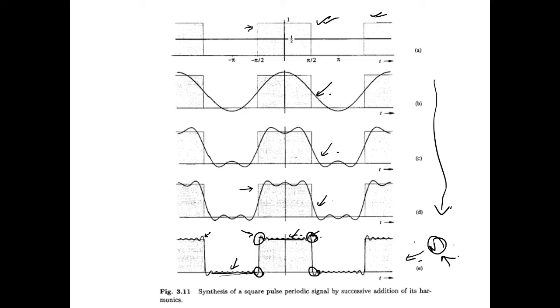Since we are restricting it, we get a signal which is as close to the original signal, but since we are not able to use an infinite number of sinusoids, there would be some deviations, and those deviations are accounted for through this Gibbs phenomenon, where there is an overshooting of the amplitude levels. Okay.